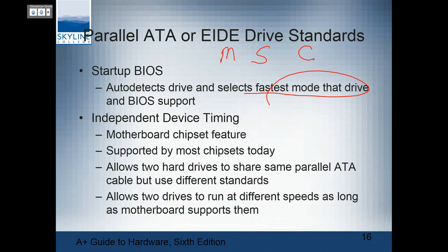And what happens exactly if they're both set to master? It won't work, because they're both trying to control everything. What does it say then? It's not going to tell you, oh, you really messed up, and you put two masters in. You're probably going to get erratic performance. It may or may not start, but the drive will not register. You may or may not get any kind of a message.